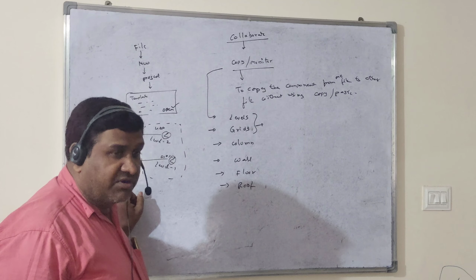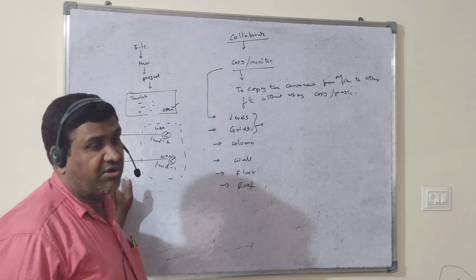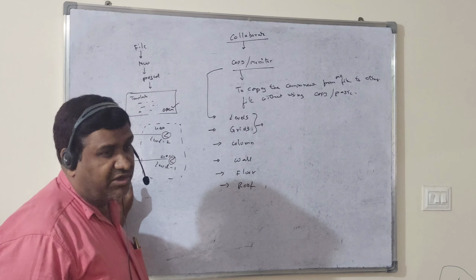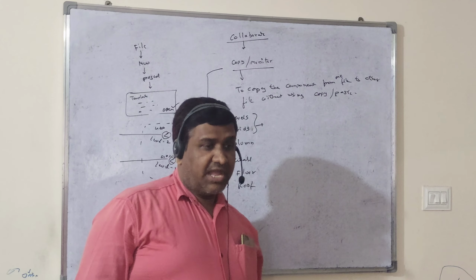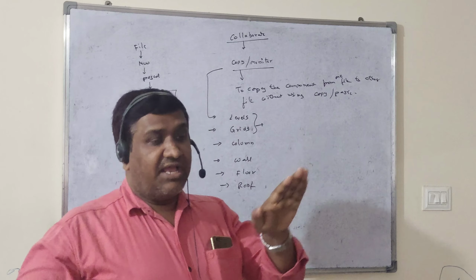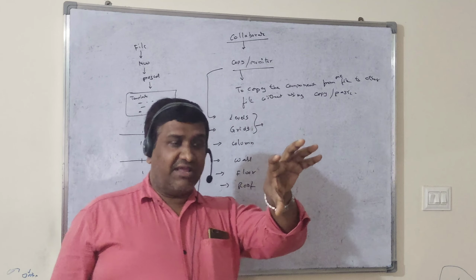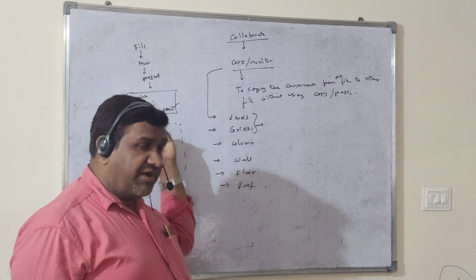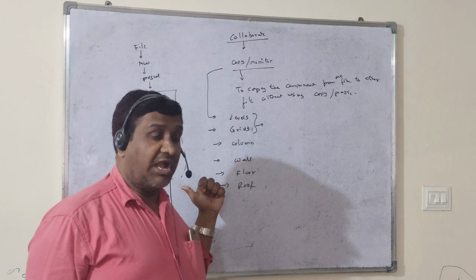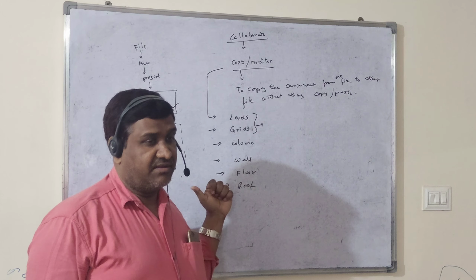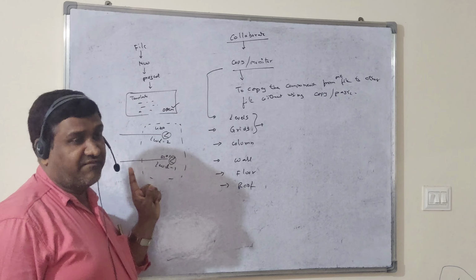First you have to select the levels, because these levels are not required for your project. Your project has a separate Revit file given, and in that file the levels and grids already exist. So you want to copy the same grids and same levels into your new project file. At that time these levels are not necessary, so you have to delete them with the help of window selection.